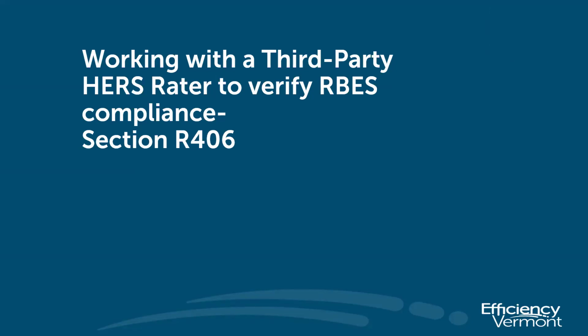Great. And next question: ResCheck is sometimes useful as a compliance method to allow trade-offs between selections. Why is ResCheck not allowed for use with stretch code? It's a good question, and there's not a specific answer to that in the code. But stretch code needing to be going beyond the base performance of the building, prescriptive compliance requires a higher points total for stretch code versus base code.